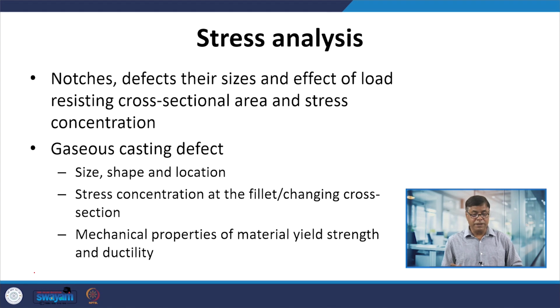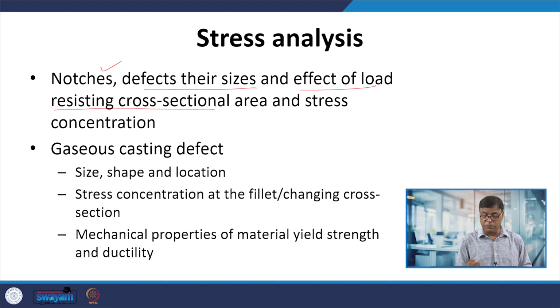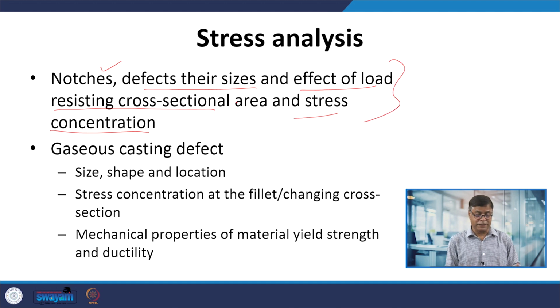Okay. So, as far as the stress analysis is concerned, what is important is, say there is a defect. The defects can be there in the form of notches or casting defects of different sizes, and the way in which they affect the load resisting cross sectional area, and how the defects are causing stress concentration. So, stress analysis needs to be done considering these aspects: the size of the defect, where it is present, how it is affecting the load resisting cross sectional area, and how it is affecting the stress concentration. That will determine the maximum stresses that will occur in the component.